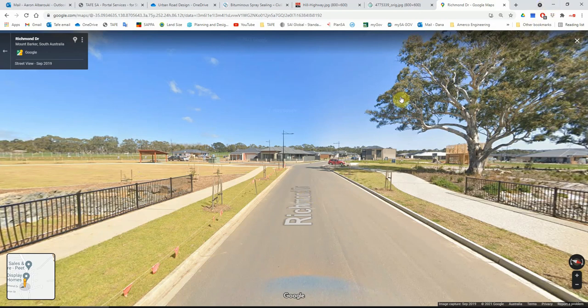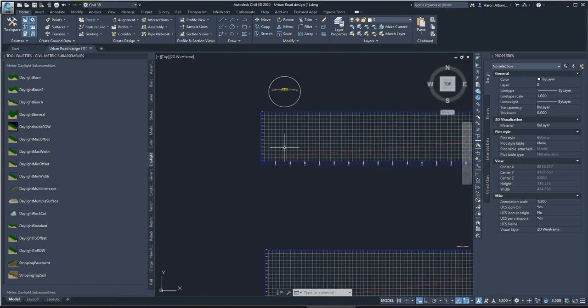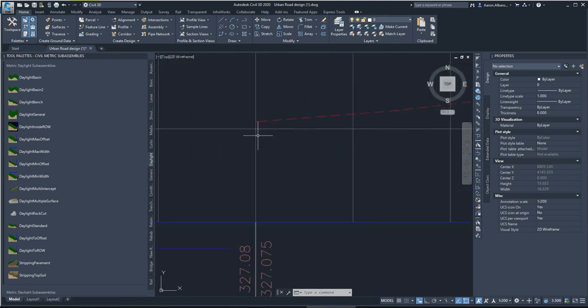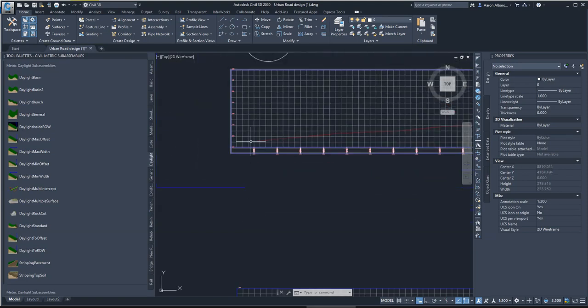So I would suggest that we create our center line of the road to be about 150 millimeters, or 100 millimeters up to 200 millimeters. Let's go with 150, lower than the surrounding surface. So how to do that? If I try to trace this existing surface and draw a profile, we can do that. That will take a very long time and will not be the easiest job to stay 150 millimeters, taking into account each one of those squares is 1 meter. So 150 millimeters roughly is that distance here. So you can go ahead and draw that, but we've got an easier way to do it.